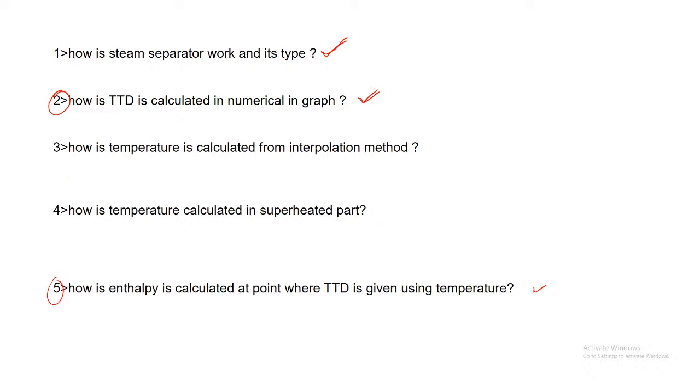So there are two chances in general. In the syllabus we are dealing with, steam power engineering, generally TTD is a very small number, positive or negative, but it would be provided to us in the numericals, or we can assume it at 0 degrees Celsius.